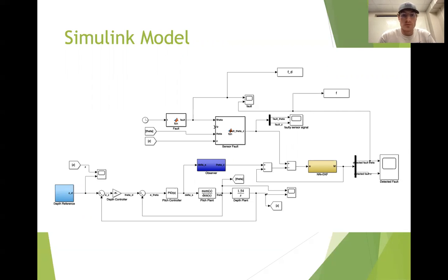And this iterates very quickly because it has to continuously vary the pitch of the rudder so that it can keep on track if there's any turbulence or anything in its path. And so there's 2 plants inside there, the pitch controller, which is labeled by PID, and then the pitch plant, which we're still working out. And that has 2 outputs, one that goes back into the outer loop, which is the depth plant, and one that goes into that observer box, the purple box in the middle.